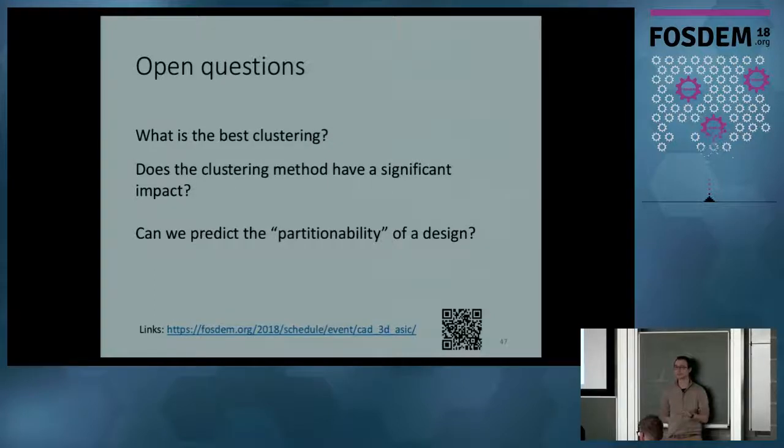You cannot yet do that because you would lack some 3D awareness in the flow. Designing your IC in 3D is the aim for the future, but in the near future we can't do that yet because we lack some tools to place and route, for example, in 3 dimensions. All the place and route tools are just 2 dimensions, X and Y. If you want a 3D aware flow, you would need to add one set of coordinates to the place and route, and that is not done yet. So no, you still need to design it in 2D and then split it.